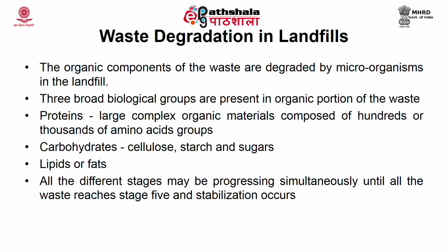In anaerobic degradation, during hydrolysis, the complex substances are broken down into simpler ones, which results in the generation of organic acids, and ammoniacal nitrogen is produced. Then followed by the next step, acidogenesis and acetogenesis take place, where the waste is broken down into volatile fatty acids. These volatile fatty acids, like acetic acid, butyric acid and propionic acid, are further converted by the acetogenic bacteria into acetates.